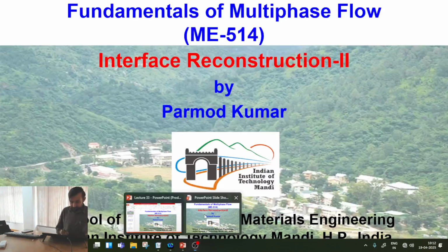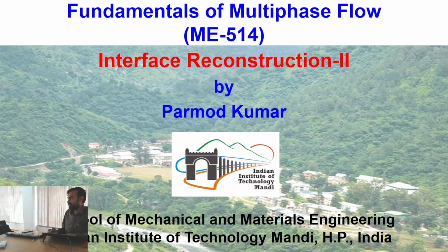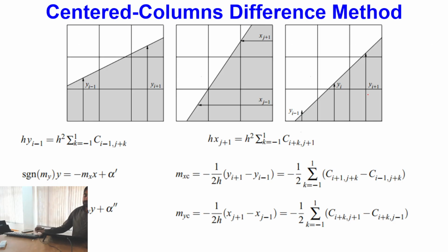Okay, good morning. So we have been discussing interface reconstruction techniques in the previous lecture. Today also we'll continue our discussion on the same. In general, interface reconstruction is one step of the volume of fluid method, where depending upon the known value of the volume fraction, we try to geometrically reconstruct the interface. And while we are discussing interface reconstruction, we are using the PLIC approach, piecewise linear interface calculation based approach, for reconstruction of the interface.